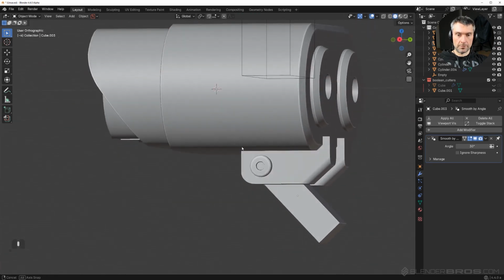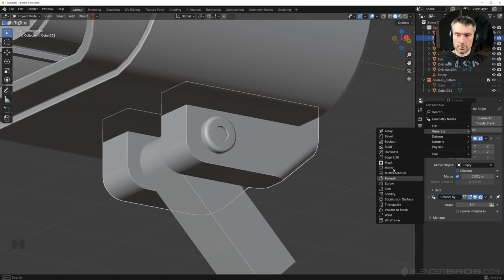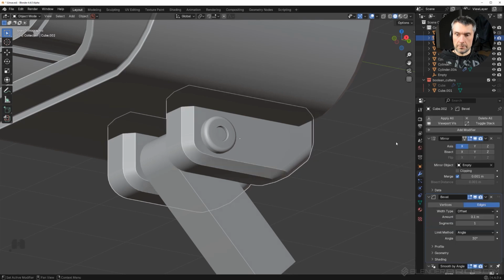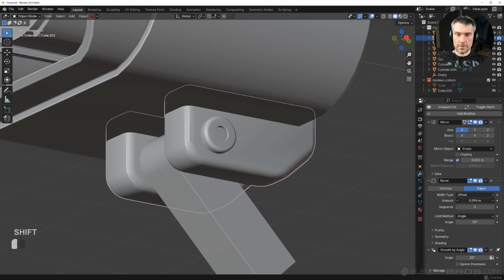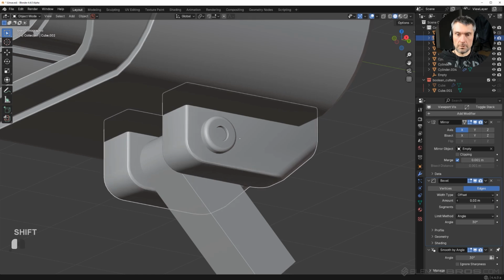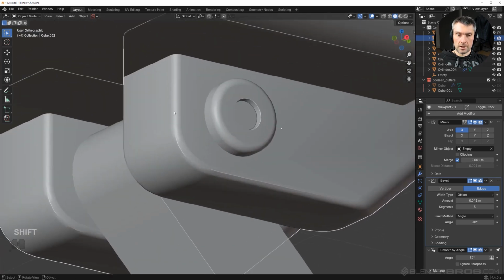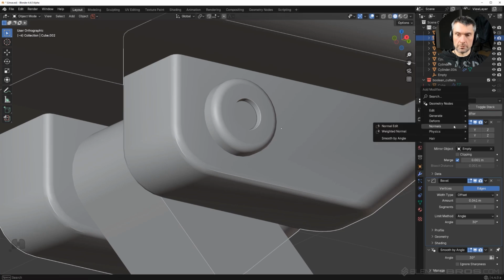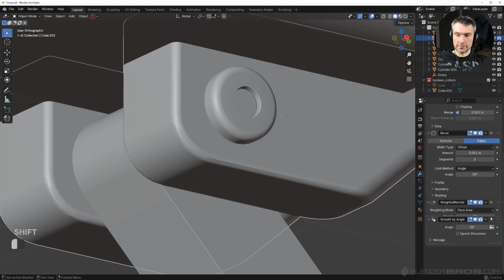Obviously we need bevels because it's very bland. So let's go here and add a bevel. Let's go to generate and bevel, and then we're going to again have to add 3 segments. Let's change this bevel to something a bit smaller. It could be a bit thicker than the other one, kind of a slightly smoother design here. You see, that's an issue with lack of weighted normals. So let's go to normals and boom, problem solved. And obviously auto smooth has to be above.